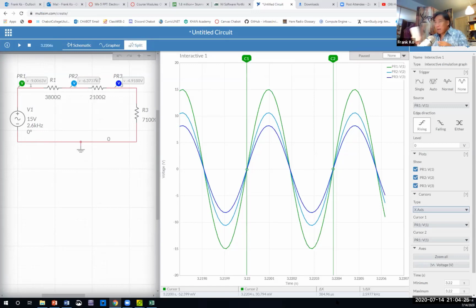Key that into your calculators right now. Key in 384.96 micro, so second exponent -6, and enter that. While you have the number of microseconds, the time, can we immediately calculate frequency by reciprocating this number? So hit the reciprocal key and hit enter. And what do you calculate? Your calculator should show you